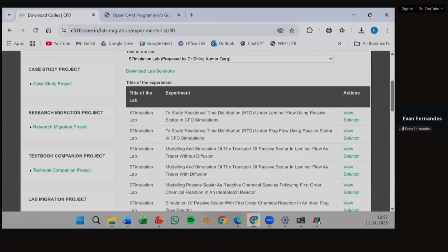In any case, how do we decide which solver to use for a particular case? Because there are a lot of solvers. Okay. When you're trying to modify a solver, there are some parameters and equations that you will require. In our case, we wanted to introduce a scalar, and we also wanted to solve for energy and the Navier-Stokes equation, that is your flow equations.